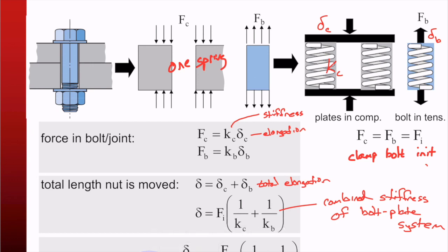And so this leads us to the technique, which we call the turn of the nut method, which is much better. A lot of times, if you see really good instruction manuals, the specifications will always say hand tighten plus 1/4 turn, or hand tighten plus 1/2 a turn, or hand tighten plus 3/16 of a turn, or whatever, right?